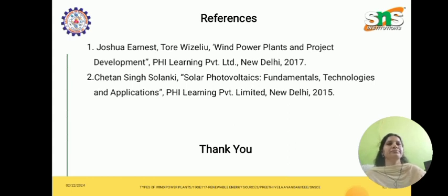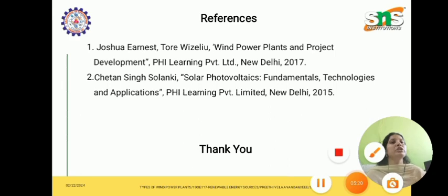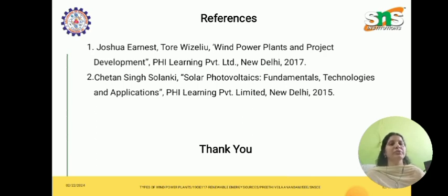The conclusion is that the most significant difference you should note is that the HAWT has its axis of rotation parallel to the wind stream, whereas the vertical axis wind turbine has its axis of rotation perpendicular to the wind stream. Both these types of wind turbines use the kinetic energy of blowing wind to drive an electrical generator to produce electricity.